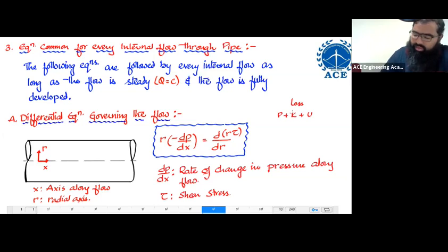You see, kinetic energy will never sacrifice. Why will kinetic energy not sacrifice? Kinetic energy will say, as I move from here to here, the cross-section area here and here, both of them are same. If cross-section areas are the same, then according to continuity, because I have to satisfy continuity first, A1V1 equals A2V2, my velocity will be same. He'll say, okay, he is not sacrificing.